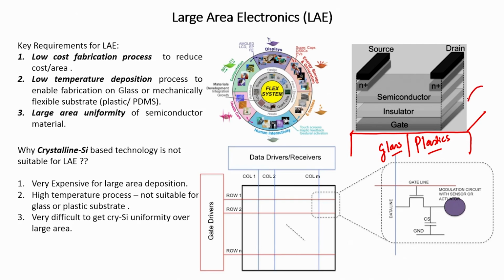We first deposit a very thin metallic film that will constitute the gate of the MOSFET. We will then deposit a thin film that constitutes the insulator, and then a thin film that constitutes the semiconductor, and this would constitute the metal insulator semiconductor stack. And then we have our source drain electrodes, which if required would need the doping of the semiconductor or some kind of treatment in order to ensure low contact resistance and a good injection of carriers.